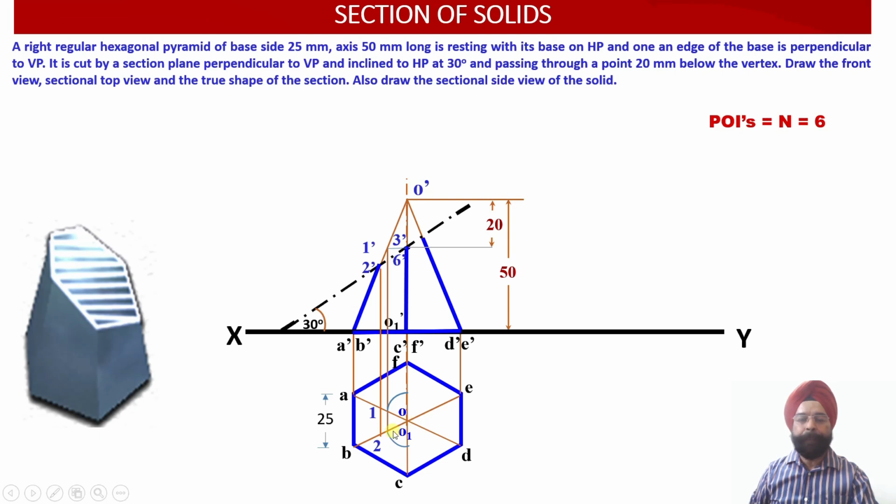Similarly, open compass this much. Obviously this radius and this radius, they are the same. Again, keeping needle over here, open compass this much, and then draw an arc to meet OC over there, so that this true length of the radius is shifted onto the plan projection for the OC. Similarly, true length of this radius for 6 has been transferred to the plan projection of OF. So this gives me point 6, this gives me point 3 over there. So this is the same thing which we did even in the case of section of cones over there.